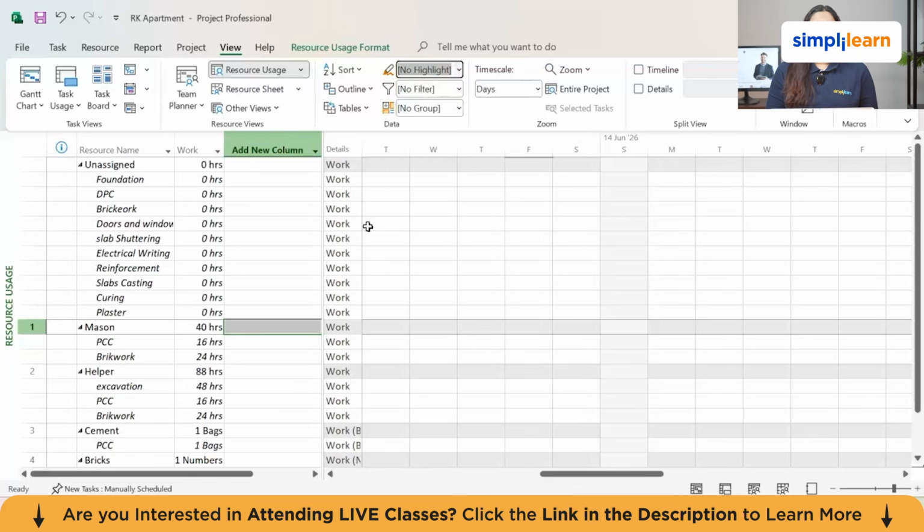Now the biggest question that comes into the picture is how filter and grouping change how you communicate. A construction project manager's job is not just to manage the schedule. It is to communicate it efficiently to multiple audiences. Subcontractors do not need to see the entire program. They need to see their activities, the activities of the trades before them, and the milestones they have to meet. Filter by resources, group by WBS, and then print. That's it. That's their look-ahead program.